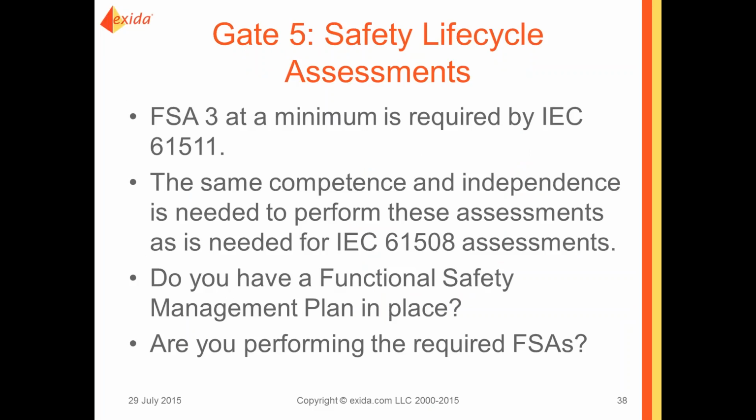And then finally, the implementation of safety lifecycle assessments is a good way to make sure you're not missing something. So FSA 3 as a minimum is required by 61511, and that's a functional safety assessment prior to the hazard being present, after the systems are designed, installed, but prior to the hazard. The same level of competence and independence is needed to perform these assessments as is needed to perform a 61508 assessment. And so the questions are, do you have a functional safety management plan in place? Are you performing the required functional safety assessments as either designers and builders of the plants or operators of the plants?